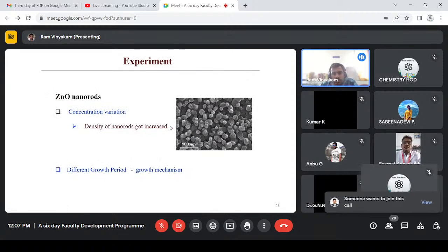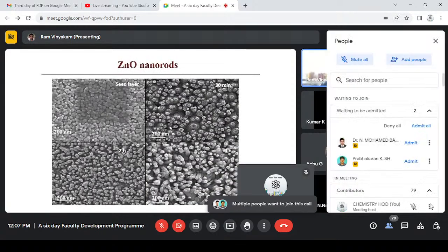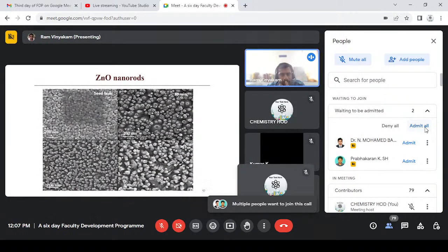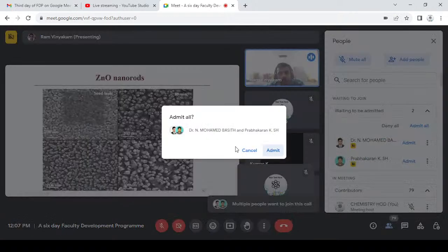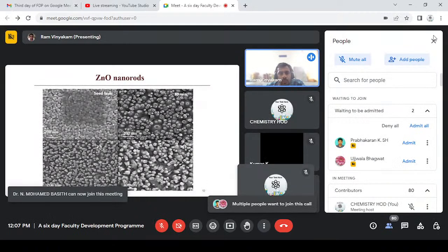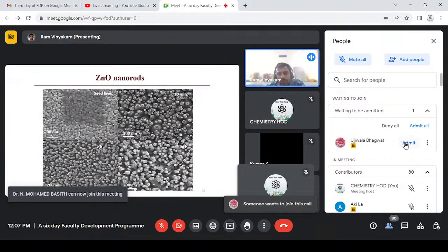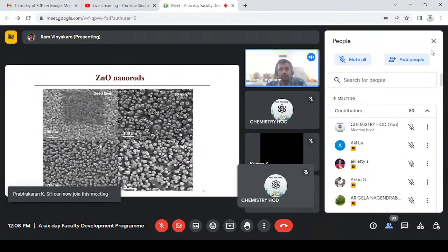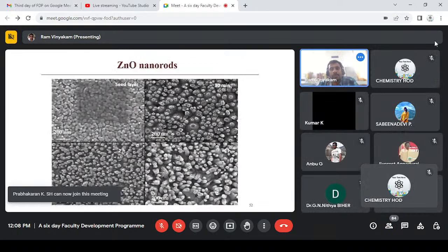And since both processes want to establish a growth mechanism, we also tried our best to go for analysis in terms of establishing the growth mechanism. And our interest in the influence of the seed layer was a long time before, probably 15 years ago. If you see the seed layer, we grew this with a simple solution by taking zinc acetate and methoxy ethanol with monoethanolamine stabilizer. We coated the solution by spin coating at around 3000 RPM.